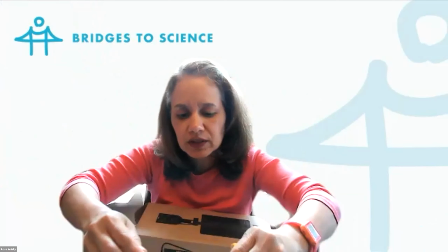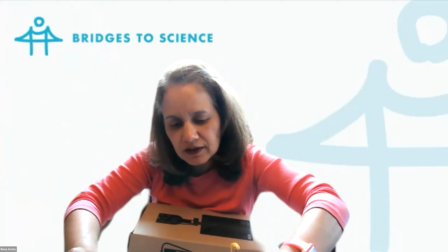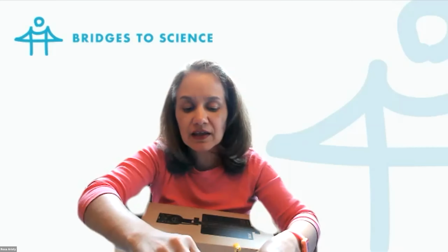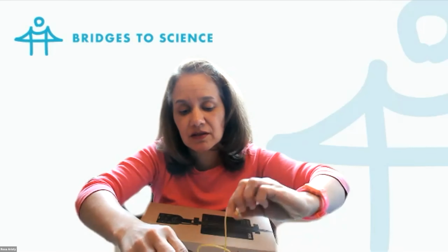Oh, that's such a relief. At least it's just the alligator clips, right? Yeah, that works. So black works fine. I think it's maybe the red. Let me double check now. Another thing that can end up happening is through handling the clips, you might have ended up reestablishing a weak connection. So I would say let's stick with the yellow and green.